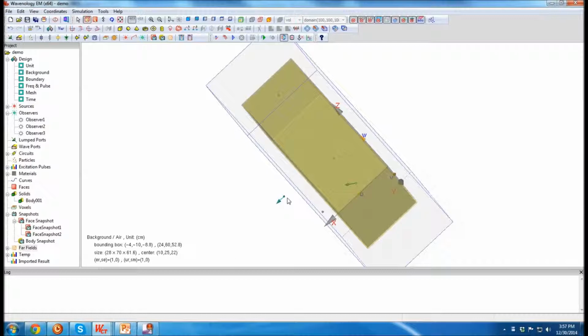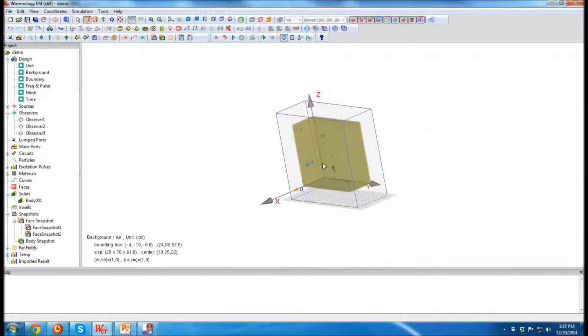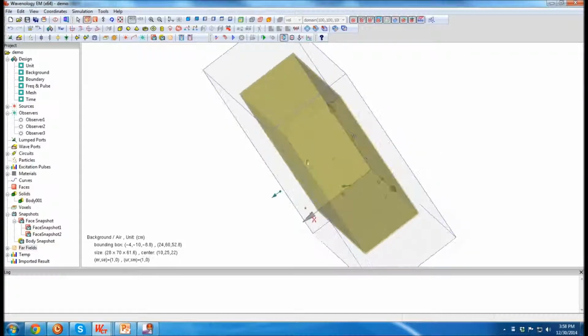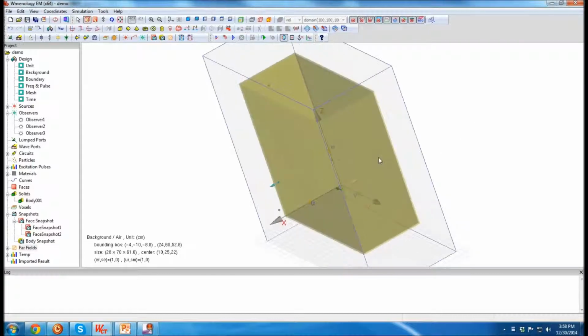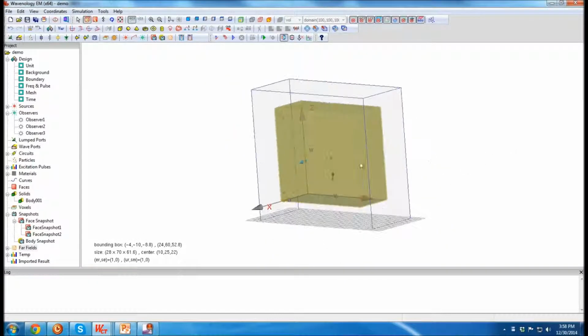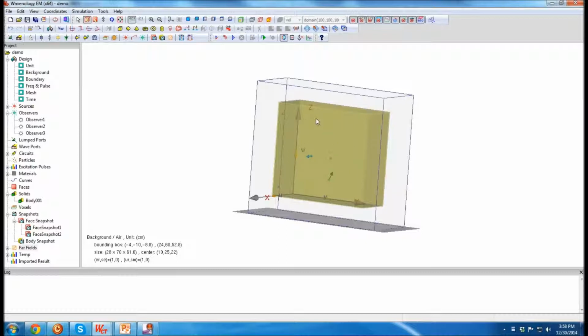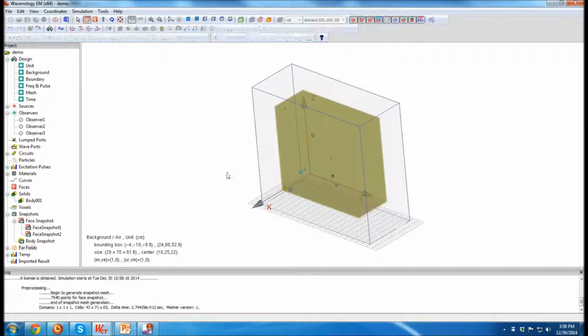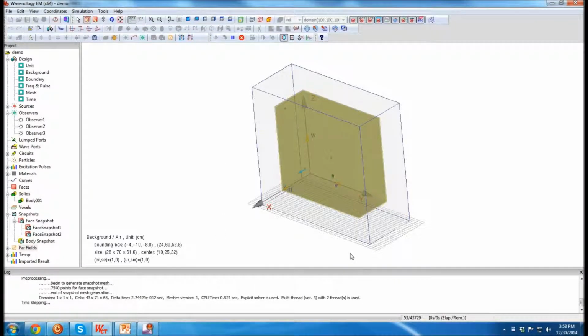Actually, it's 30 meters away, but you can't really draw the indicator 30 meters away. That's too large, too far away. So we just put in the position direction indicating this is the observer point of the far field. Okay. So that's pretty much it. We can start a simulation and check out the results. If you click this button right here, it will start to simulate.